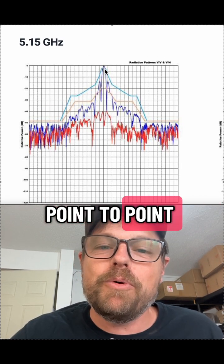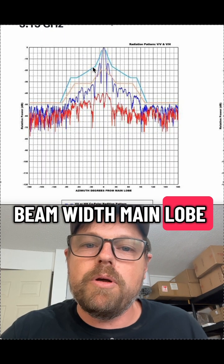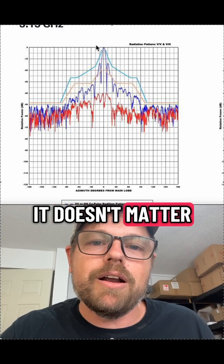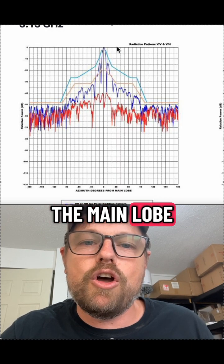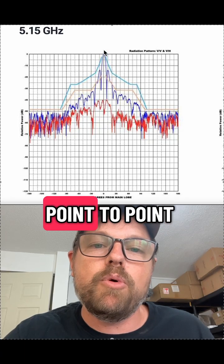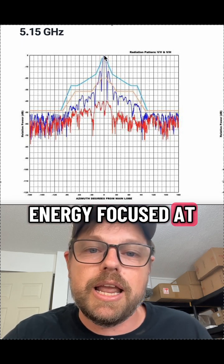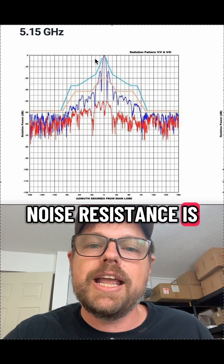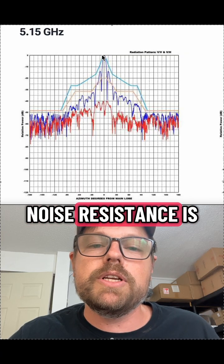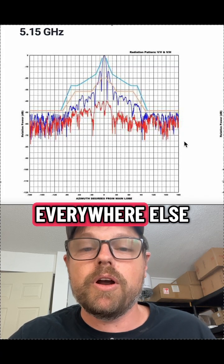But particularly in point-to-point applications, the Ultra horn has a 10 or 15 degree beam width main lobe. That's looking like a main lobe that looks like this. It doesn't matter if that energy is contained in the main lobe or in the side lobes. What you want is the energy focused at a specific point in a point-to-point application. You want as much of that energy focused at a single point. Noise resistance is not having all the energy in the main lobe and no energy in the side lobes. Noise resistance is having as much energy at the specific point and as little energy everywhere else.